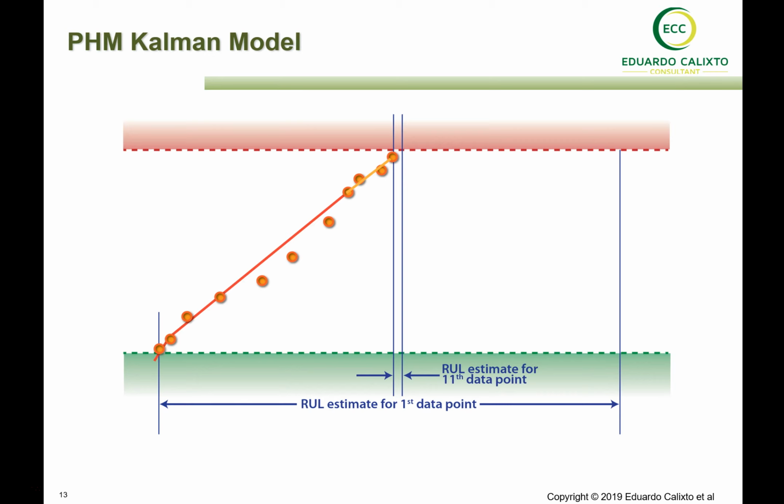Of course, if we have prognostic health management, we will be able to have our remaining life prediction updated along the operation time, and whenever some condition occurs, the compressor, for example, operates over the usual operation limits, such a remaining life will be updated automatically.